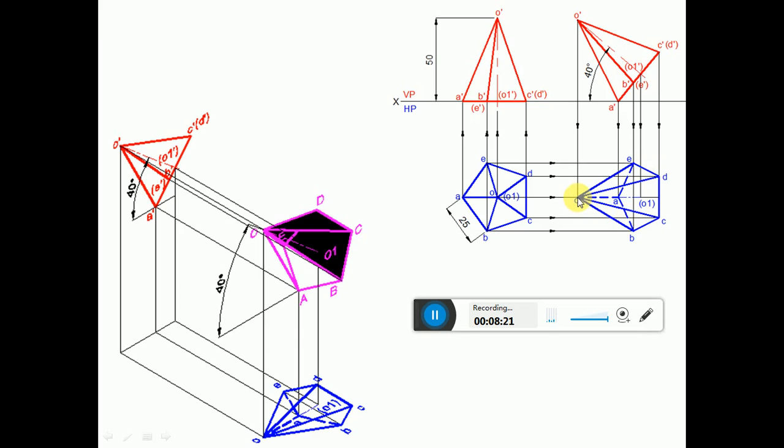So here all the exterior edges of the boundaries of the solids are visible. So which is the boundary? OB, BC, CD, DE, EO is on the boundary. So you dark them. Then once you look from the top view, O dash C dash D dash is a triangular face which is visible because when you look from the top view, OCD is near to the observer, so it becomes visible. So you dark OC and OD, which is a dark line.